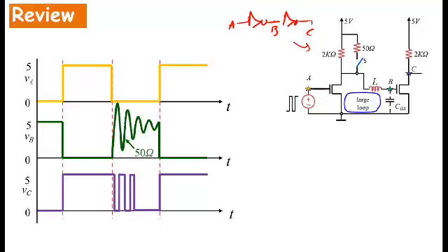And we said that if I applied voltage A at the input of the first inverter, and if I try to speed up node B by turning on switch S, and have a small resistor, 50 ohms, in parallel with the 2 kilo ohms in order to speed up my circuit, what I observed was a waveform that looked oscillatory like this. And all that we have seen so far does not quite prepare us for this.